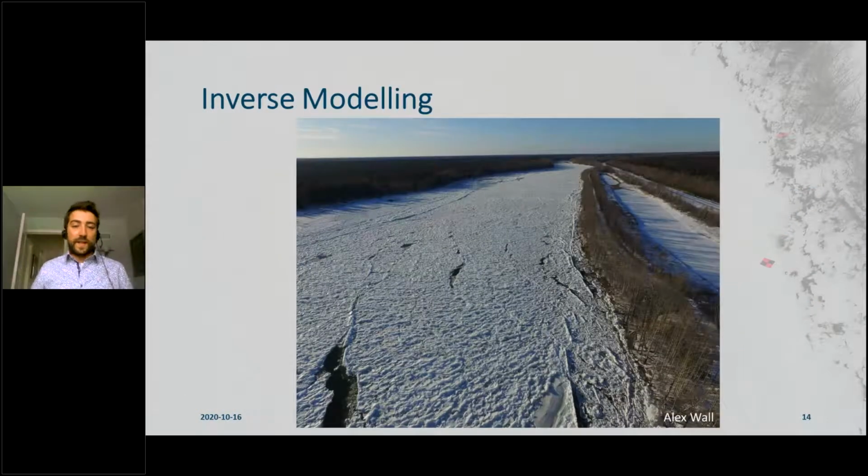How do we then test them to see if they're any way representative of our surface? Well, we used inverse hydraulic modeling. We've got good instrumentation and historical data on the site, including water surface elevation, flow, and quite a few ice thickness measurements. So I constructed a simplified 1-dimensional model based around Manning's equation. So just a really basic cross-sectional approach to the hydraulics there, where we're plugging in the water surface elevation and just finding out which ice roughness is required to match the observed flow.